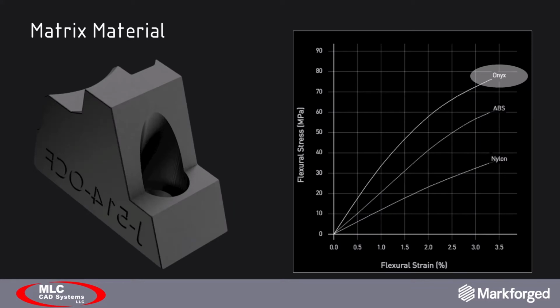Let's first talk about some of the basic materials that they were using in the Markforged printer. The matrix material that we use is called Onyx. Onyx was developed by Markforged, and by definition, it is a composite in and of itself. It consists of a mixture of nylon and chopped short carbon strand fiber. Interestingly enough, the chopped carbon fiber was not added for strength specifically, but more for stability and printability. The short strand carbon fiber helps prevent drastic changes as the material is heated and cooled, thus resulting in beautiful, accurate parts, which was very big for Acme Audio.